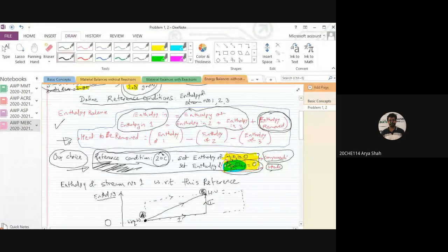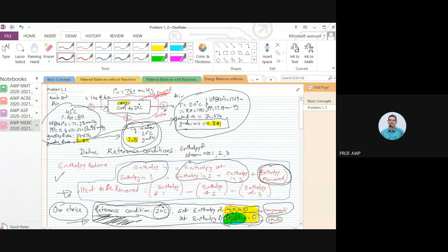So actually the problem that I was facing was that I was keeping the state dynamic. Yeah, and I understood what you're trying to do, but that's what I'm trying to say, that you don't have to worry about it because enthalpy is a state function. I have to only worry about the control volume over which I'm applying the enthalpy balance. And then I have to only worry about what comes in and what goes out, not how it goes from in to out. Okay, sir, but still it's difficult for me to visualize.